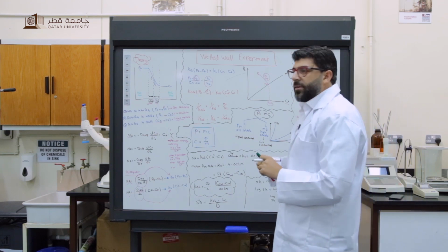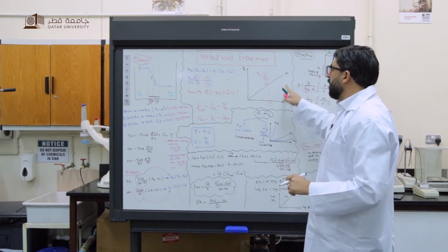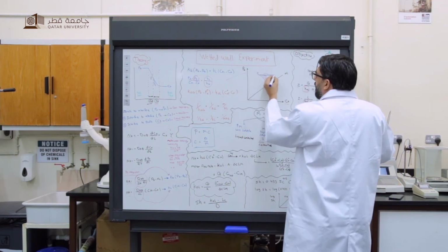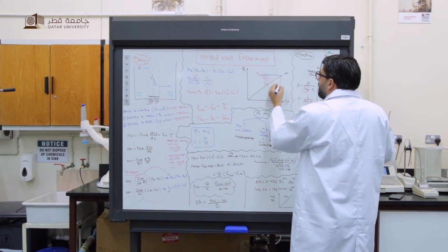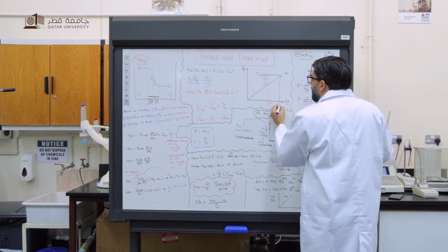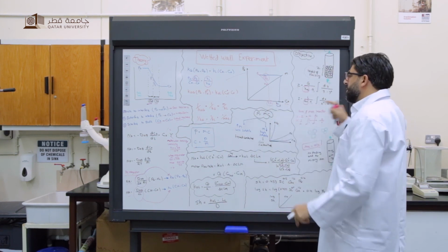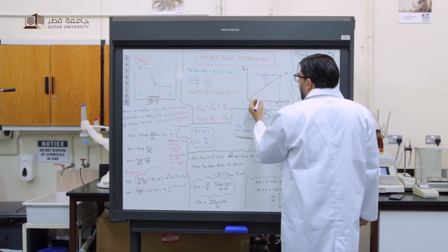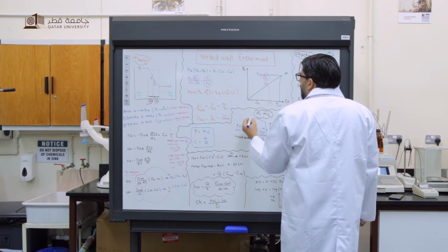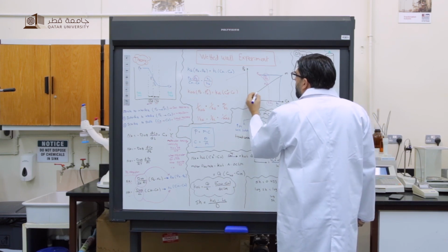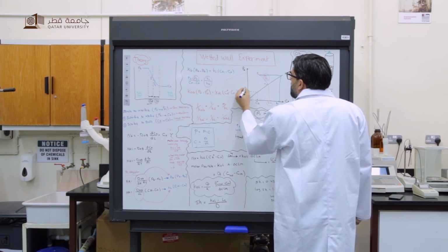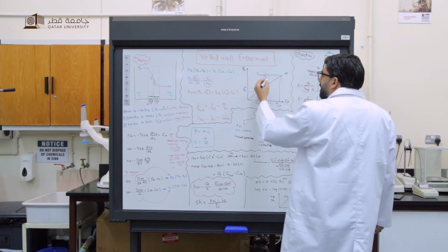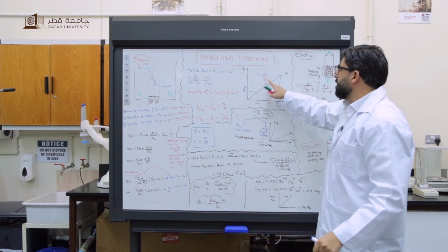So I can use another technique that depends only on the M, on the equilibrium line. So PA, if I extend the line here, and find the related, this one will be CA star. So it's the theoretical concentration of A that is in equilibrium with PAI. And also, if I have CA, I can find the related PA star using the M line. And it will be easier because I don't need to find both KL and KG, the individual mass transfer coefficients.